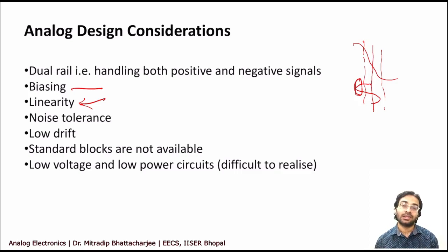While amplifying the signal, it may also amplify the noise. The noise in the first stage will go to the second stage and be amplified. Then that noise will go to the third stage, and the noise from the second stage also goes to the third stage. In that way, the noise will keep increasing.